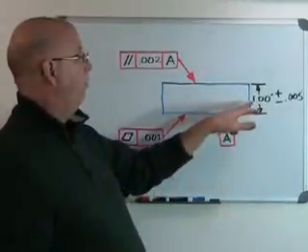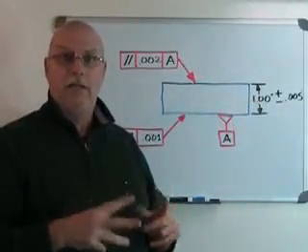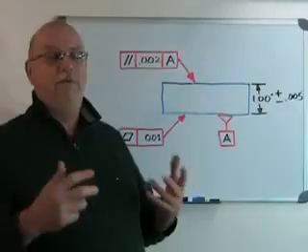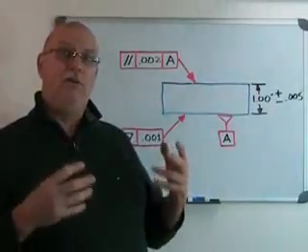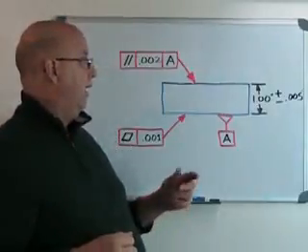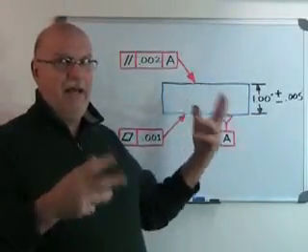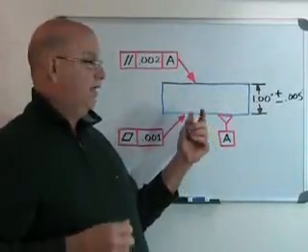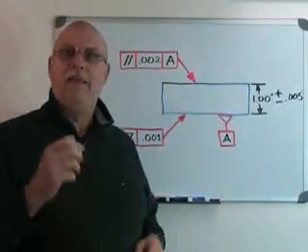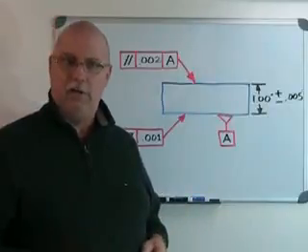In other words, I would have put 1 inch height, but with a plus or minus of a few 10,000ths, with the hope that that would end up giving me 2 parallel surfaces. And because it would have been incredibly accurate, well, it would have been very expensive to produce. That's the beauty of geometric tolerances.